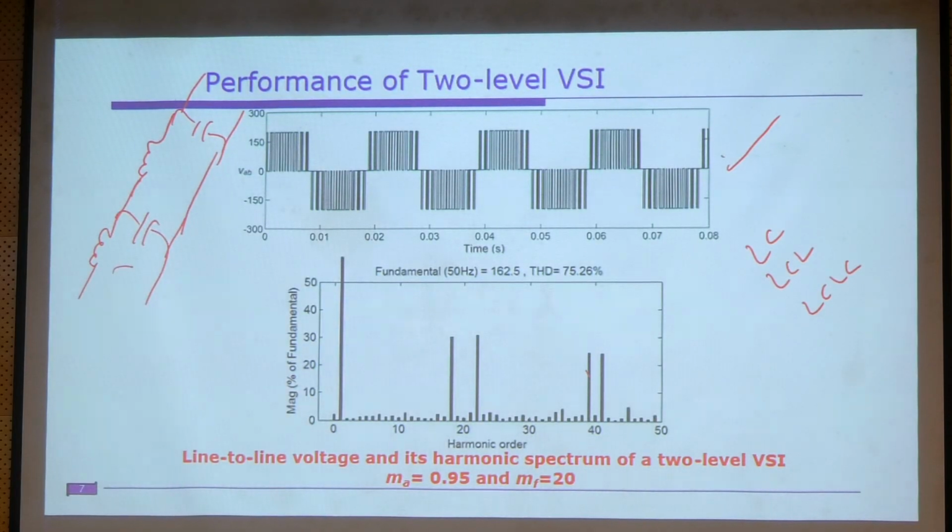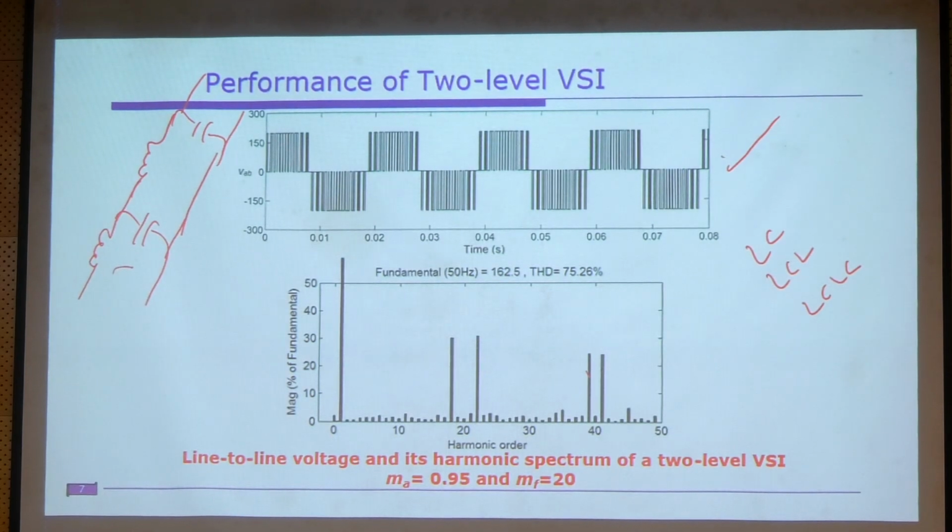One component commonly affecting reliability is the capacitor. The capacitor is based on electrolytic properties. After 1 or 2 years, the chemical properties inside the capacitor will be altered. Therefore, the resonant frequency or its actual capacitance may deviate, which gives you wrong tuning, so the tuning may not be at a perfect level.